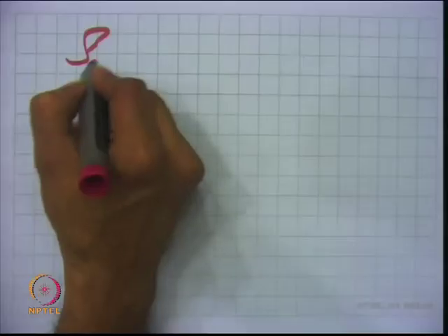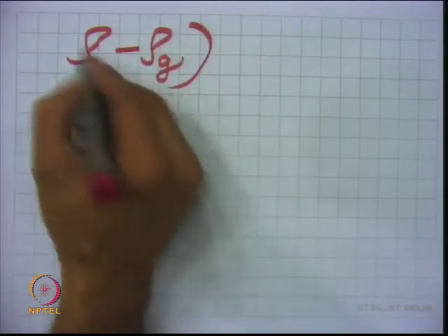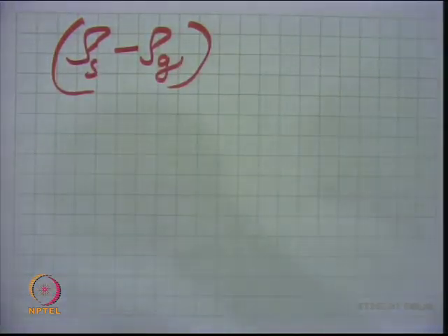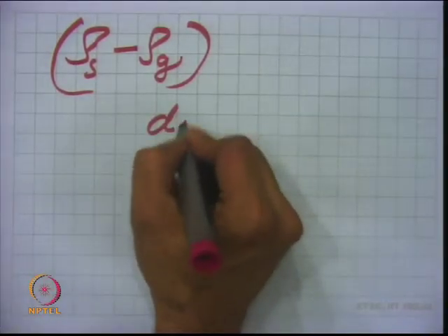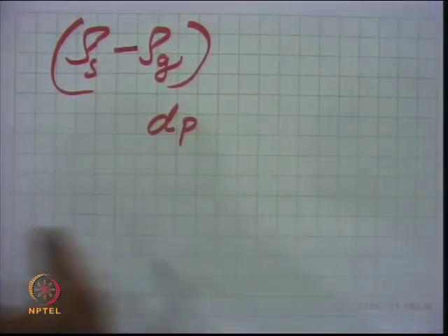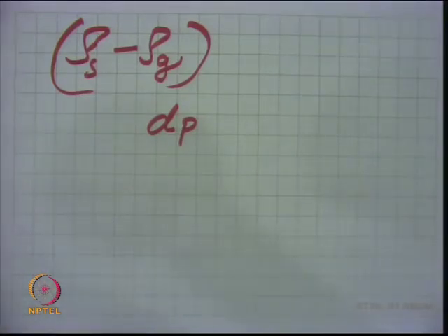And when the particles are very fine, all of it will depend on the size of the particle, that is the first thing. I told you that there is a buoyant force, a viscous force, and gravity force. So, it will depend on the viscosity of the medium, the density of the gas, and of course the superficial gas velocity, which is very important. It will also depend on rho s minus rho g, the density of the solid minus the density of the gas, and the size of the particle is very important, right. So, you need to characterize these things before looking at the type of fluidization behavior, and it will also depend on the properties of the solid.